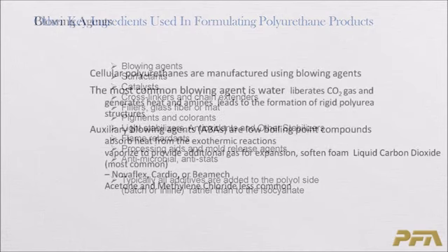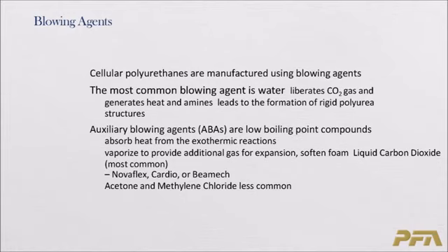I mentioned that to make the foam, you need a blowing agent, and typically that blowing agent comes from the reaction of water with the isocyanate to generate carbon dioxide. But there's a limit there. That reaction is exothermic, and it builds the urea structure, or the hard segments. So if you want to make a really low density or really soft foam, that's hard to do with just water.